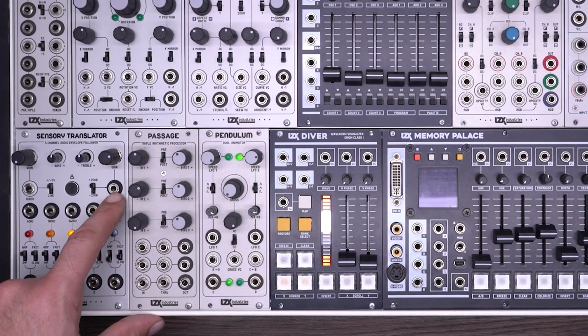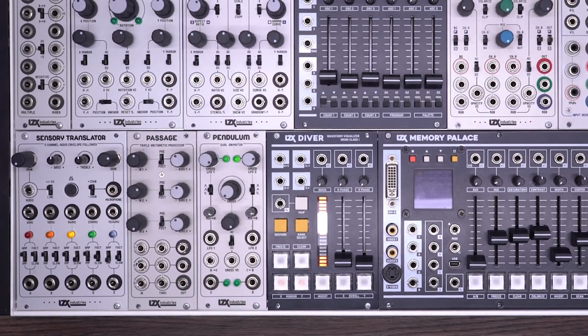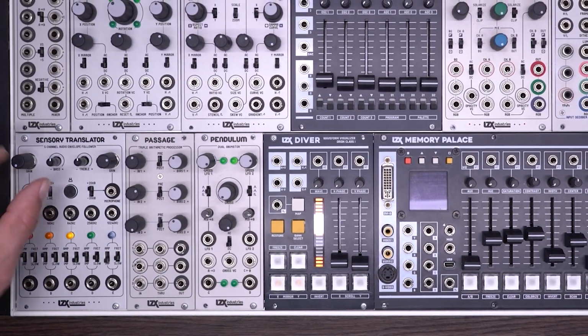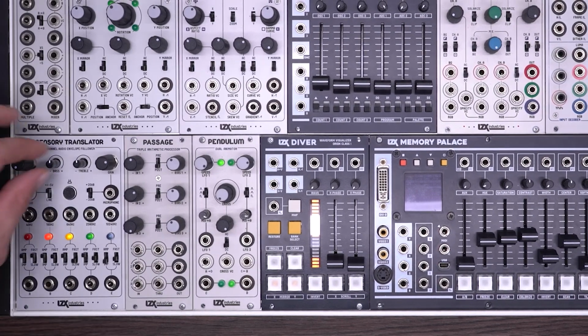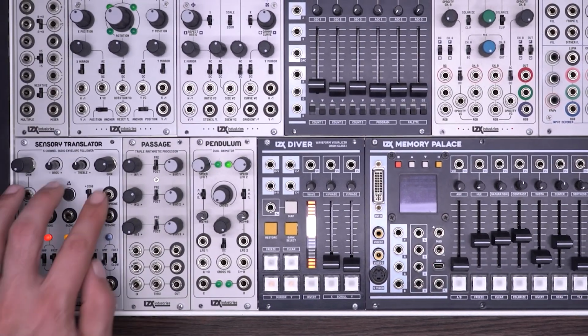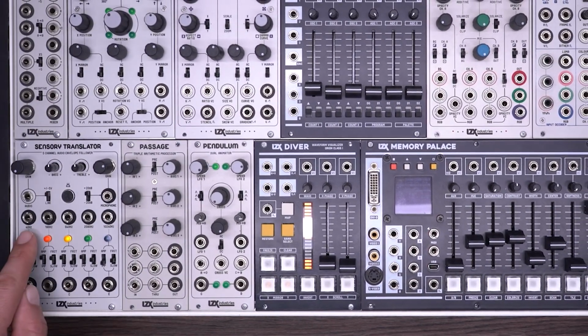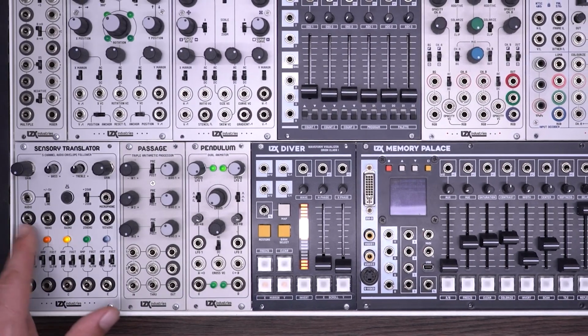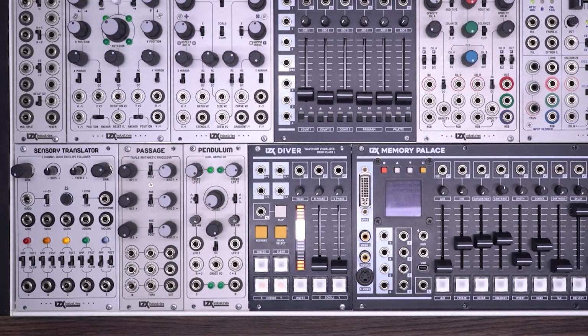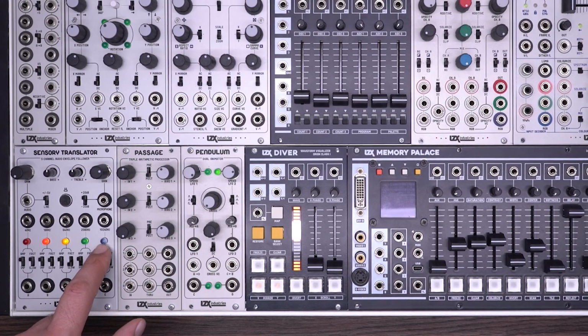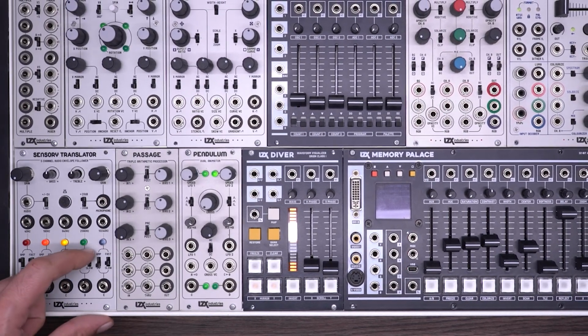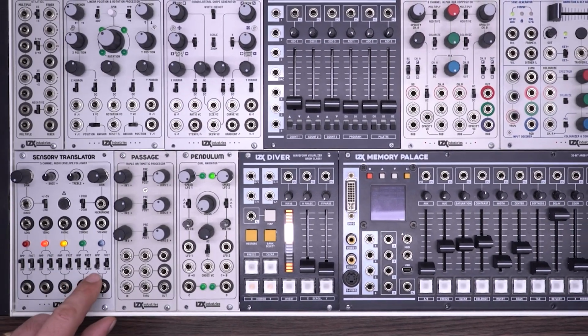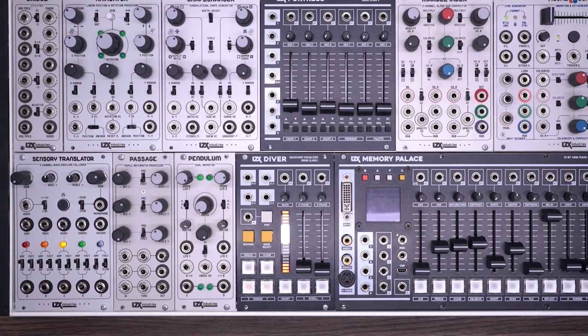It also has an output so you can patch it into other parts of your system. And each of these audio sources has its own dedicated gain knob and a global bass and treble EQ. The audio source is split into 5 different frequency bands. These can be accessed directly from the jacks on the front panel. They're also passed into an envelope follower, which can be set to either amplitude envelope or impulse envelope. We'll discuss what that means later.